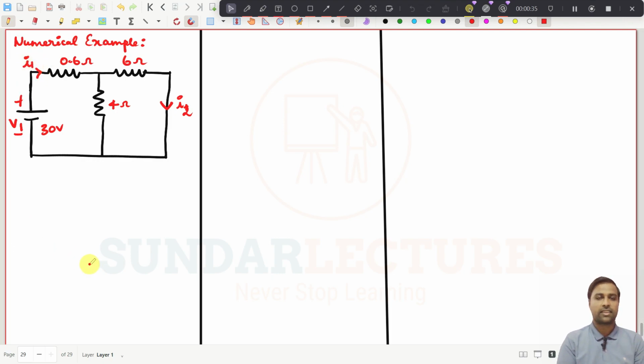I'm just taking it as I1 just to understand. Maybe how will you find this current and this current? It is very simple, right? These two resistors are connected in parallel. If you want to find the current I1, if you simplify the whole network, there will be only one equivalent resistance across this voltage source, and I can do it like this, right?